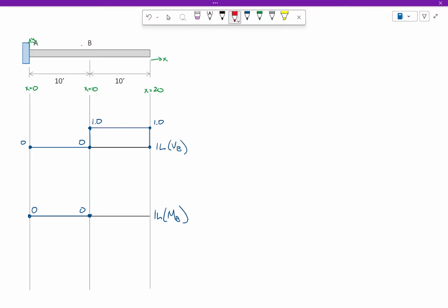We put a hinge at the point of interest, right? And when we do a hinge, we're trying to rotate this side some. We're trying to rotate this side some. They tend to rotate that way so that we have a total slope of 1. But I propose this side has to stay flat because this is a fixed support. It also comports with this reason here.